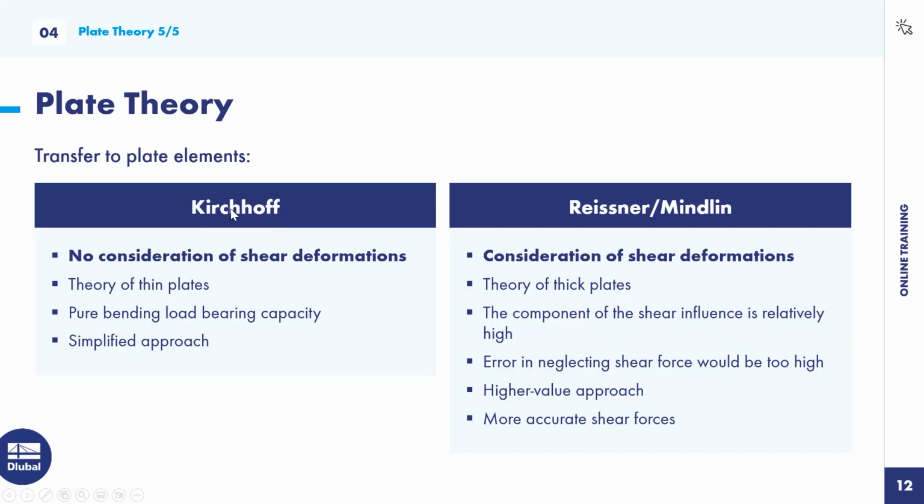However, let's stay with the Kirchhoff theory first. It's called the theory of thin plates, since as we learned before, the higher the plate, the thicker the plate, the higher will be the influence of those shear deformations. That means this Kirchhoff theory is limited to thin plates.